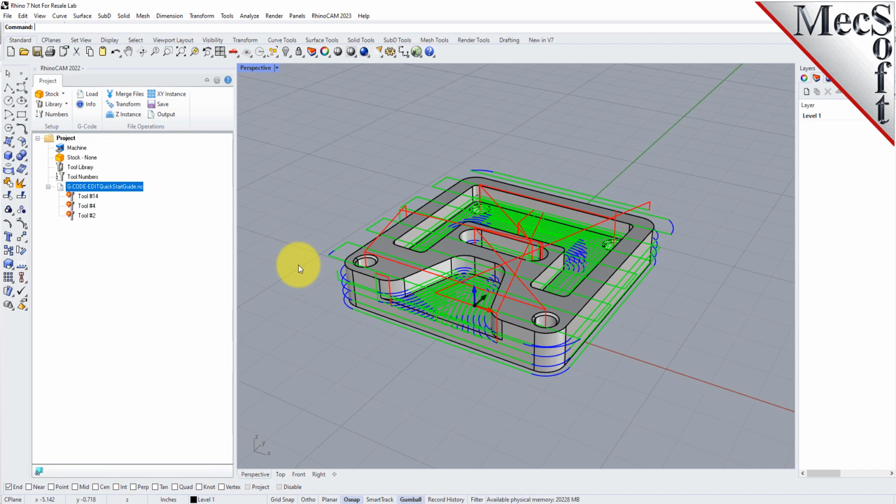That's because in your tool library, you may have multiple tools with the same tool number. In your shop, you may have hundreds of tools, and depending on your standards and how you apply your toolpaths and tools, you may have more than one tool with tool number 1, say.